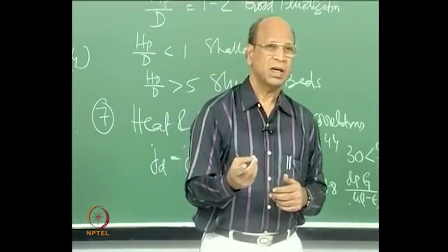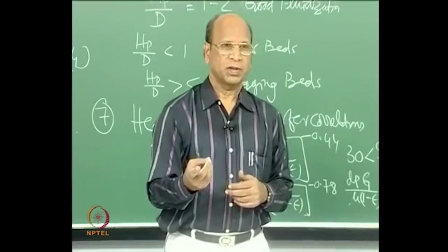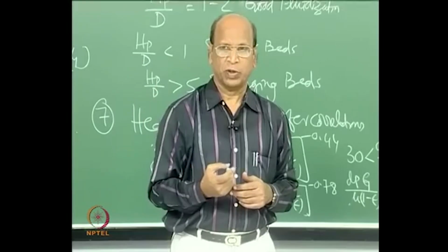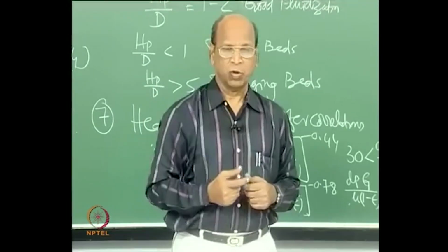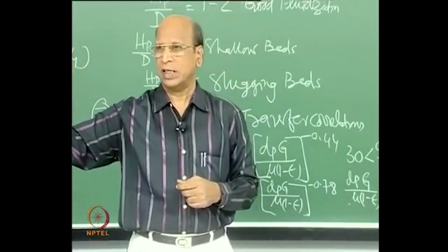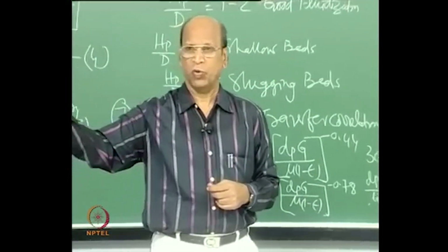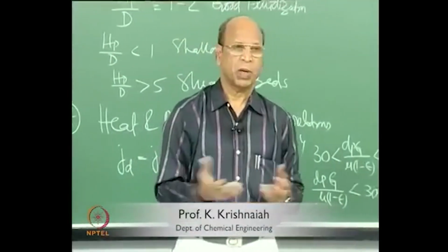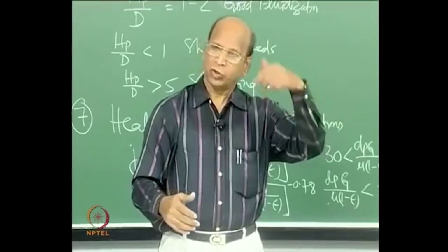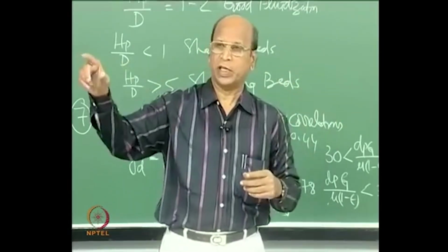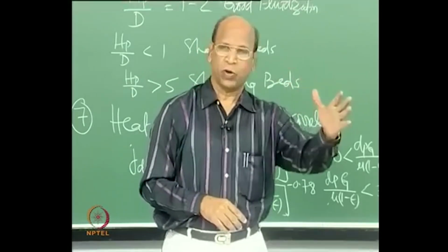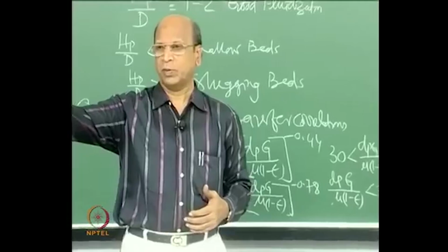One more. So many times I have drawn this, probably I would have written the recycle model. Recycle infinity gives a mixed flow reactor, recycle 0 gives a plug flow reactor. So, all the extremes are covered with axial dispersion and also the number of tanks. When n equals infinity you have plug flow, n equals 1 you have mixed flow, dispersion number equal to 0 is plug flow, dispersion number equal to infinity is mixed flow.